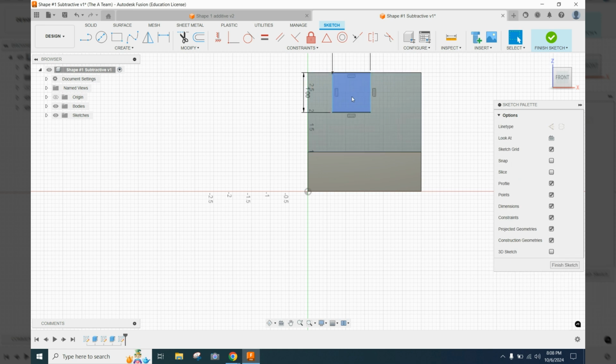This time I also need to give this rectangle a location, because you can see it's off center in my drawing. So we're going to go to sketch dimension, and I'm going to click one of the vertical lines on the edge. So it doesn't matter which line. You can see as I hover over them, they turn different colors. This one turns blue because this is our active sketch plane. This one turns more of a bold black because I'm able to select it, but it's on a sketch plane that's in front of our current one. Okay, so I'm just going to go with the blue one.